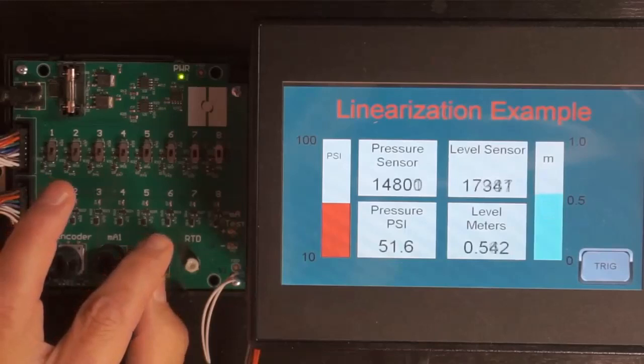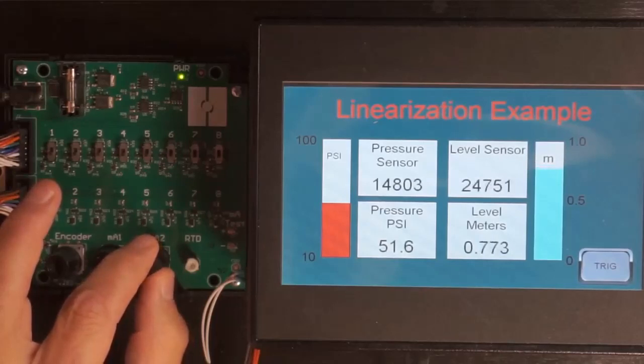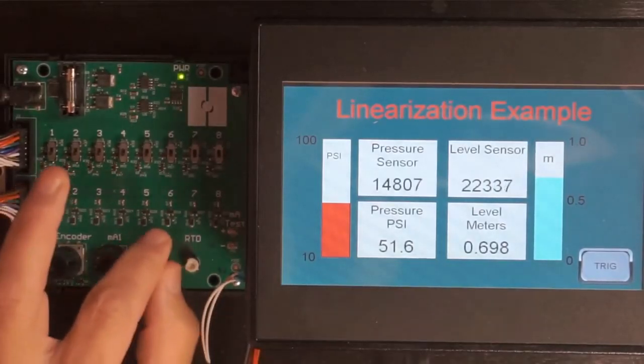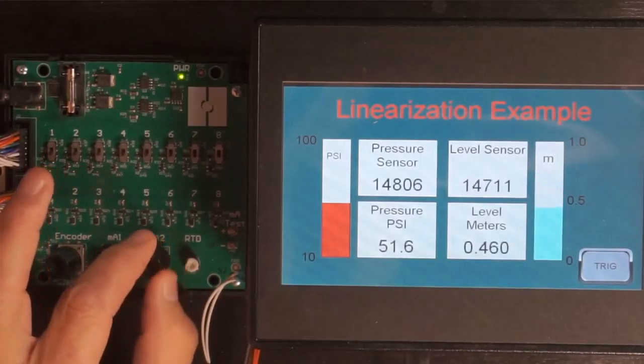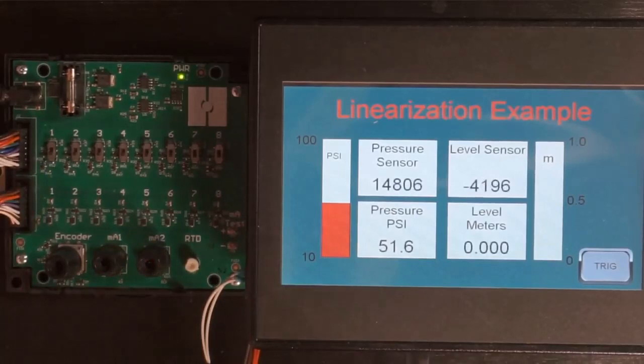Okay, but as my value increments, you can see my scaling is getting up towards 1 meter. So that's, again, simple scaling using, this time, the scale real function. There's also a scale integer function that you can use. And it's definitely one of the more popular ones in structured text, at least from a math standpoint. Okay, let's head back to Cscape.